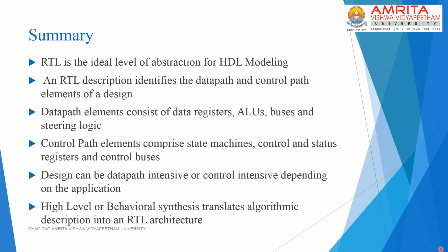So from the characteristics of an RTL model, we can determine whether a design is datapath intensive or control intensive. In datapath intensive designs, most of the design is comprised of datapath elements such as arithmetic circuits, registers, and steering logic. And control is implemented using very simple circuits such as sequences. Datapath intensive designs are usually found in applications such as digital signal processing, image processing, and video processing.